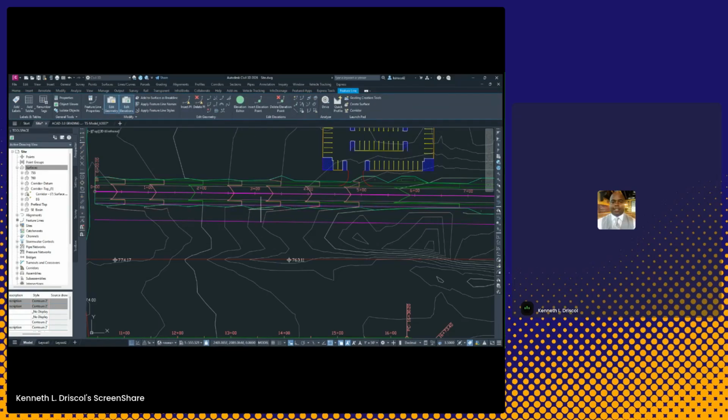And I'll say do a stepped offset. And then I'll say 50 feet. And then I'll pick that side. And then it says go a grade. And I might just say negative 0.5.